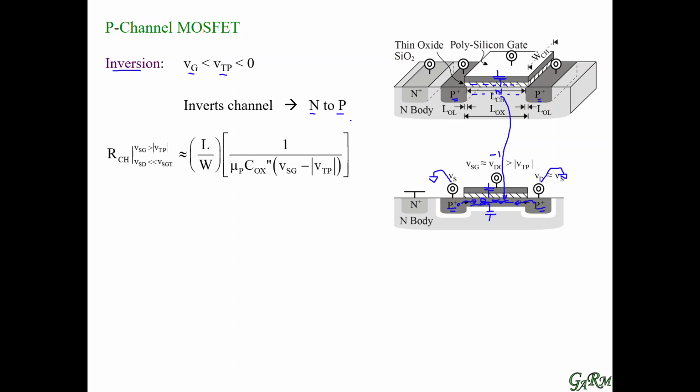So in inversion, then we have a resistance between these two terminals, and that resistance is going to increase with length, and decrease with width, and that's if we make this device wider basically into the screen. What we see here is that now when we induce current flow, we can induce more current across that width. So it decreases the resistance the wider the channel is.